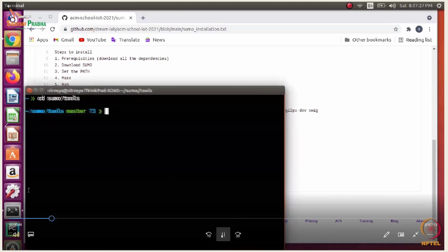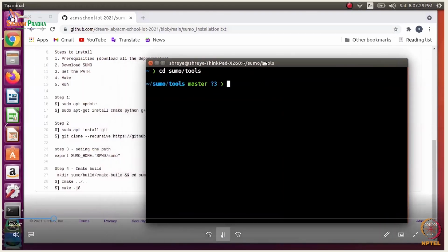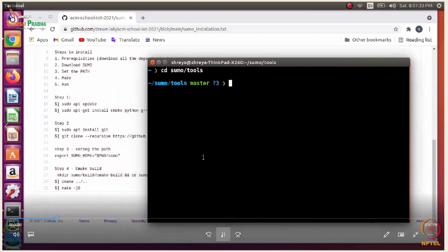So I'll just show you how to do that. You can do Sumo simulation manually as well by giving XML files of your nodes, edges, and the connections between them, and give some commands to get it to run. We will be using OSM Web Wizard here to get the UI of Sumo.